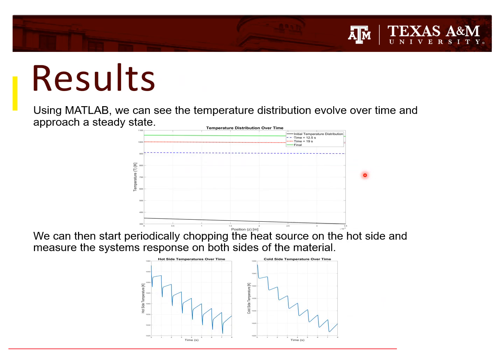The first case can be seen in the plot above, where we start with an initially linear temperature distribution throughout our material. As the heat sources are applied, this will cause a rise in temperature and force the temperature distribution to change. It will eventually reach a steady state where the convective input and the radiative loss are balancing each other, which will cause the material to remain at a constant temperature and constant temperature distribution.